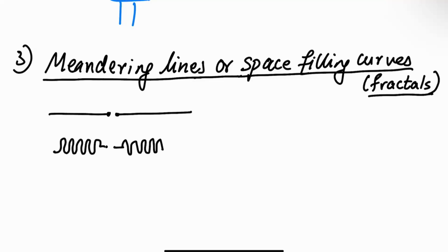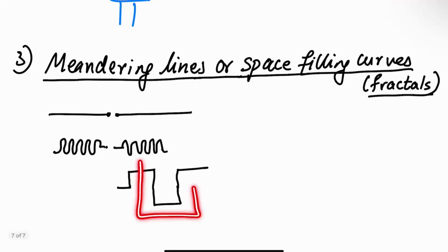And if you pay close attention to this, what's happening? When I'm meandering something, I'll just zoom into one meander. Maybe we'll zoom into this section. I have a current here that's like this. Use a different color. A current like this here, like this here, this here, like this. So only these polarizations add up. These currents add up in the far field and these currents cancel.